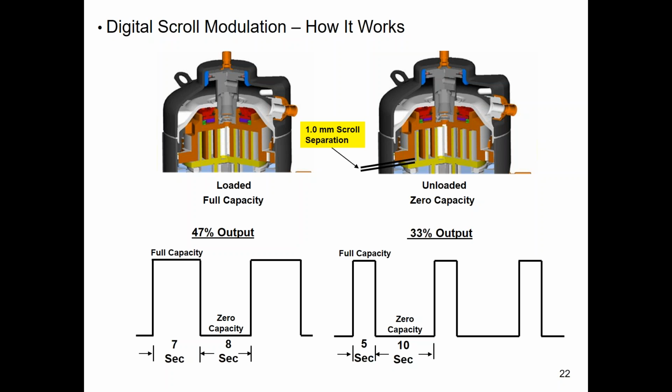What if you wrap the pipe in heat trace tape? Obviously it's not efficient and it's stupid to heat the ground with a bunch of electric heat, but yeah. Well, that's the biggest thing right there, the efficiency is horrible, and then how do you control the heat as capacity changes? I wouldn't suggest that. And how do you service it?